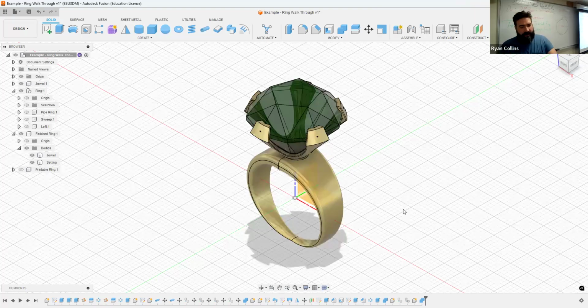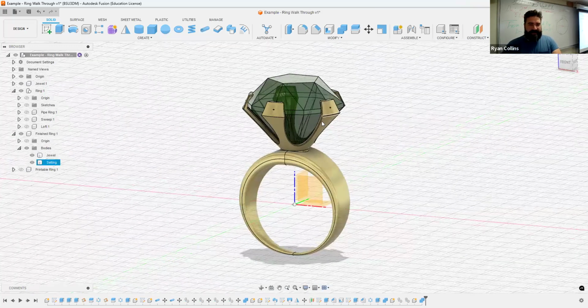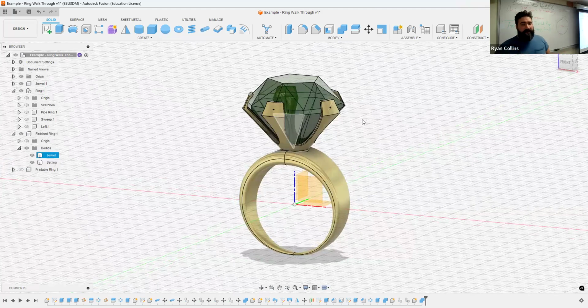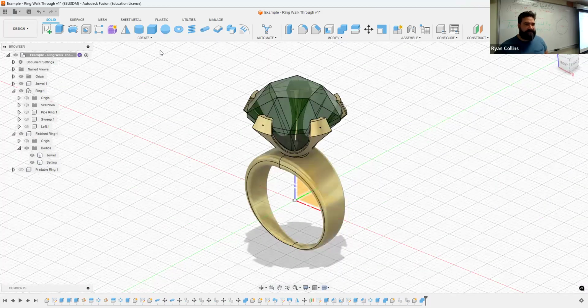So outright, like I said, the basics are we are figuring out a way to make a simple kind of jewel shape, glistening glassy there. Some kind of a setting, which is these tines locking around it. This is obviously more like ring pop costume jewelry style, but there you go. And then this ring is made by using the Loft tool, one of the three options we have. We'll go over those in a moment. But basically, Loft translates one sketch to another sketch and morphs between. Any combination you like, there you go. So let's go over these real quick.